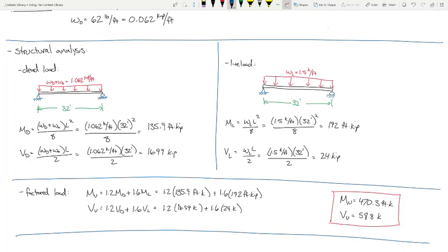Then I can't just factor the loads. I have to treat them separately. And if some of you are thinking, well, why don't I just take the load and divide it by the length and turn it into a distributed load? If you're thinking that, I want you to take your hand and do that. The answer is no, okay? Because what you're doing is changing how the moments are distributed on the beam. This is a structural analysis boo-boo. And we talked about this last semester.